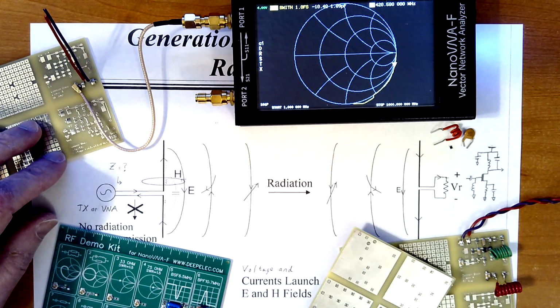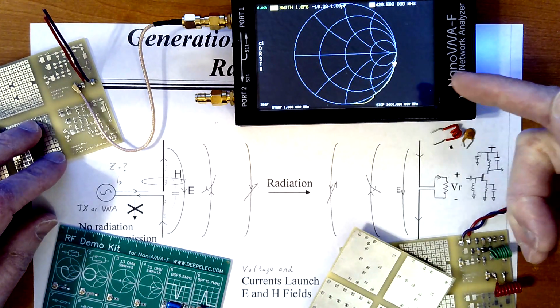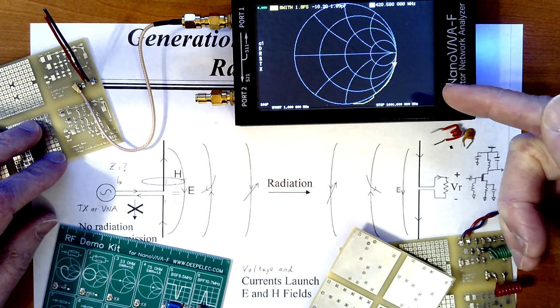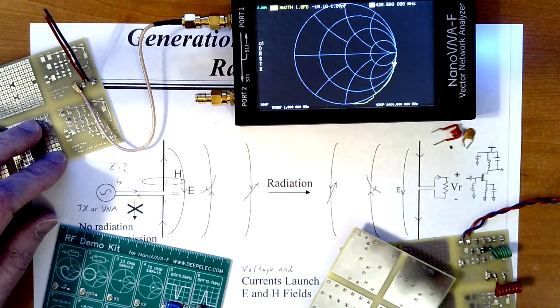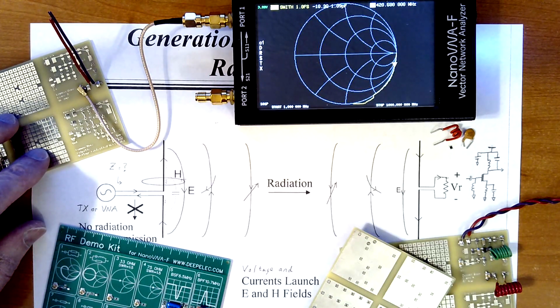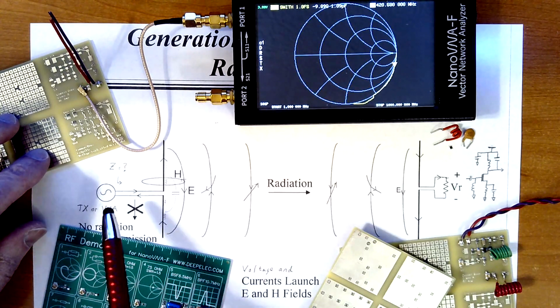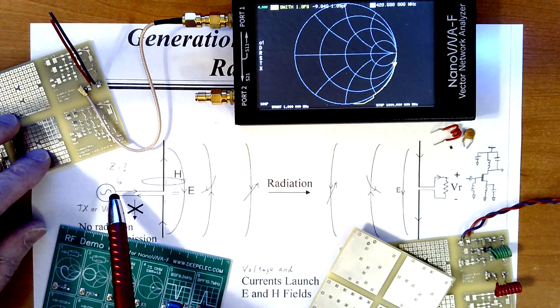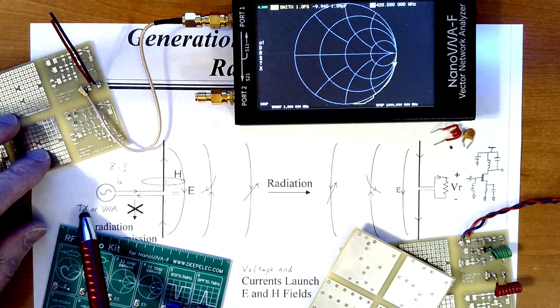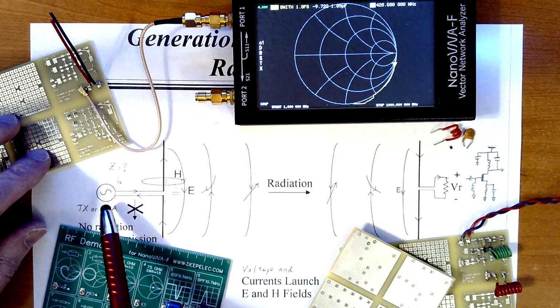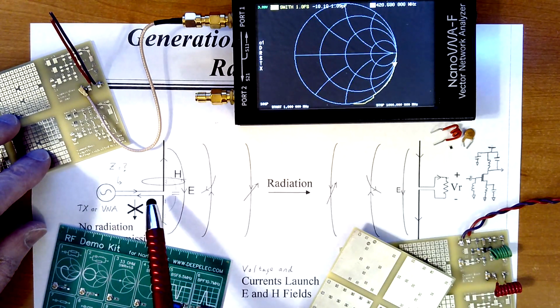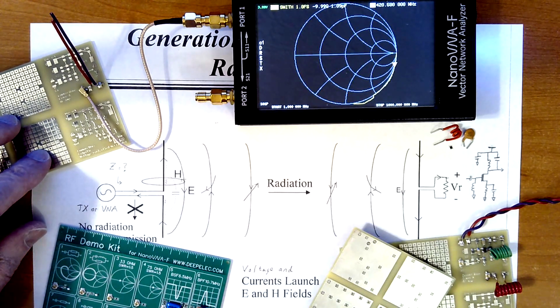Welcome back to our little mini-series on the NanoVNA, this amazing instrument that you can buy for somewhere between $60 and $140. Many of us buy these and use these to measure antennas. For example, we may want to know what the input impedance of the antenna is as seen by our transmitter. So we hook up the VNA in place of the transmitter to the transmission line and look at the performance of the antenna in terms of impedance or SWR or return loss.